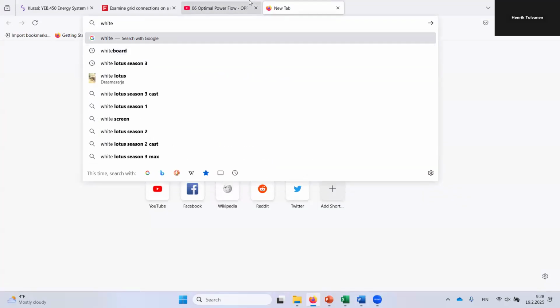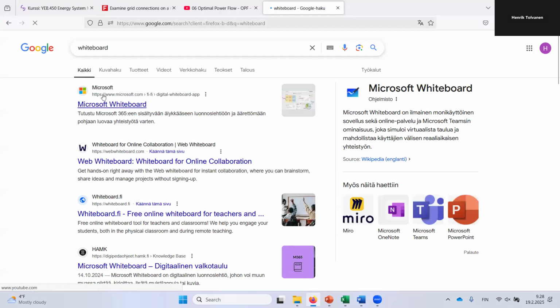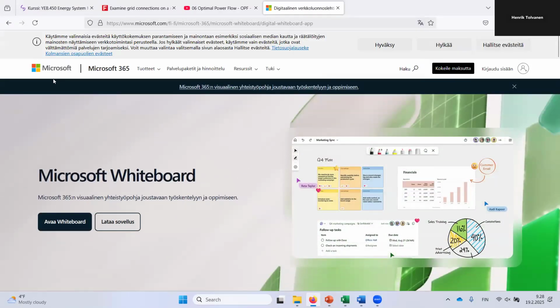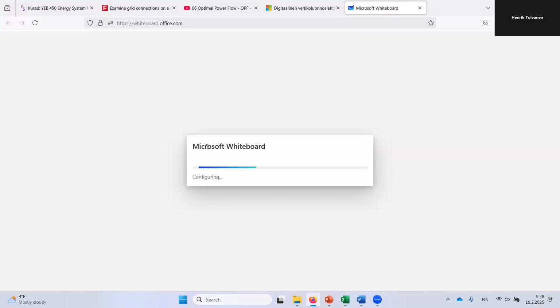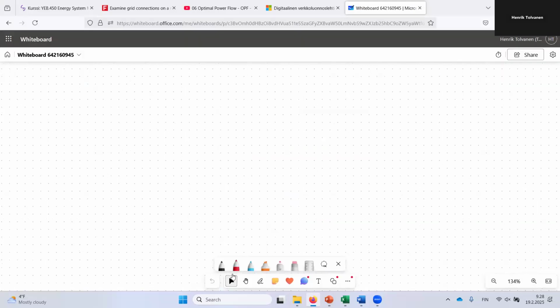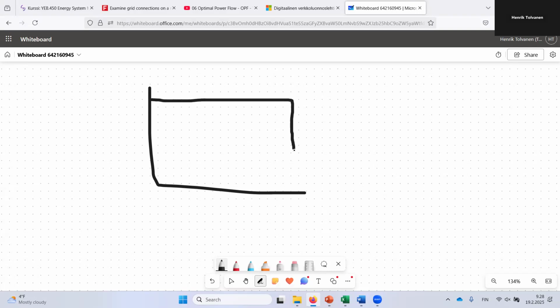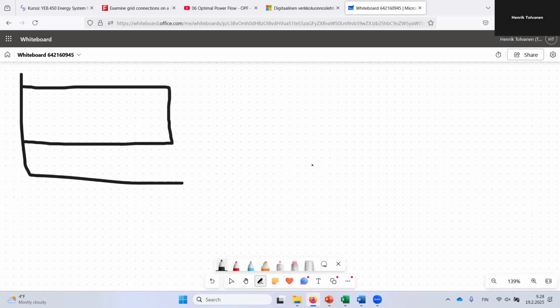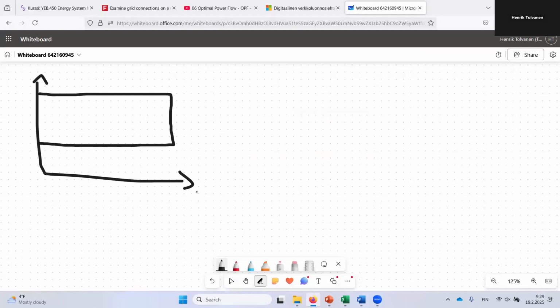Sorry? The line, will there be any temperature drop in the line itself? Yeah, if you had an infinite amount of insulation, it's going to drop just a bit, but even though the friction is taken into account, if you have an idealized system like that, the temperature would remain constant, then it would drop in the substation, and if I draw the return line backwards like this, it would remain constant. So this would be temperature, and this would be distance, and there would be the substation.